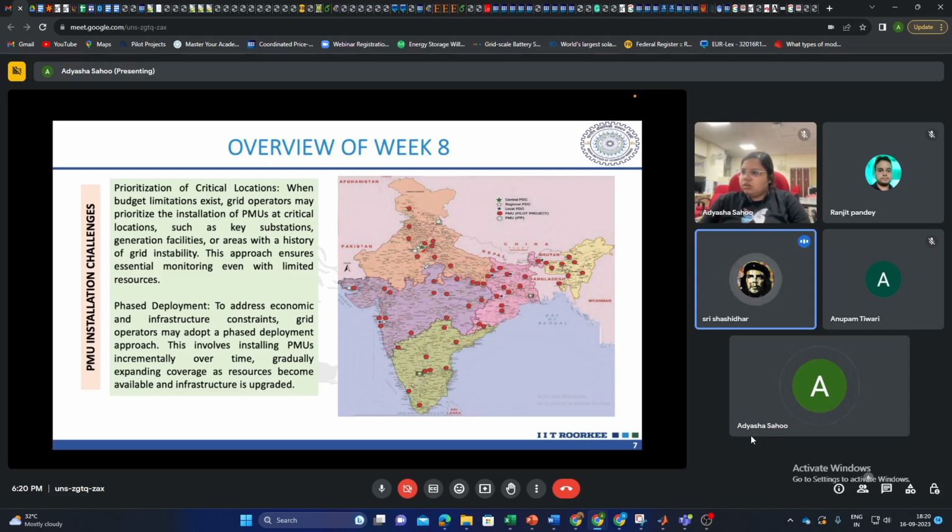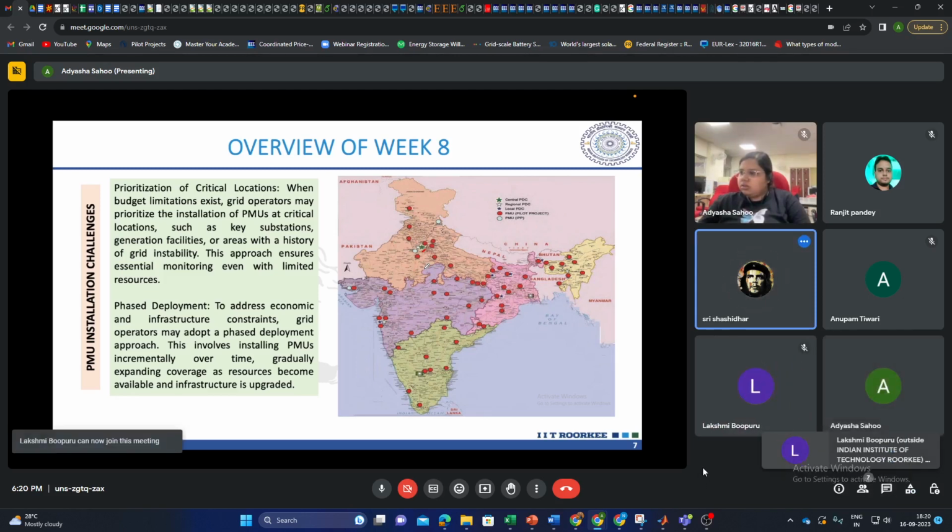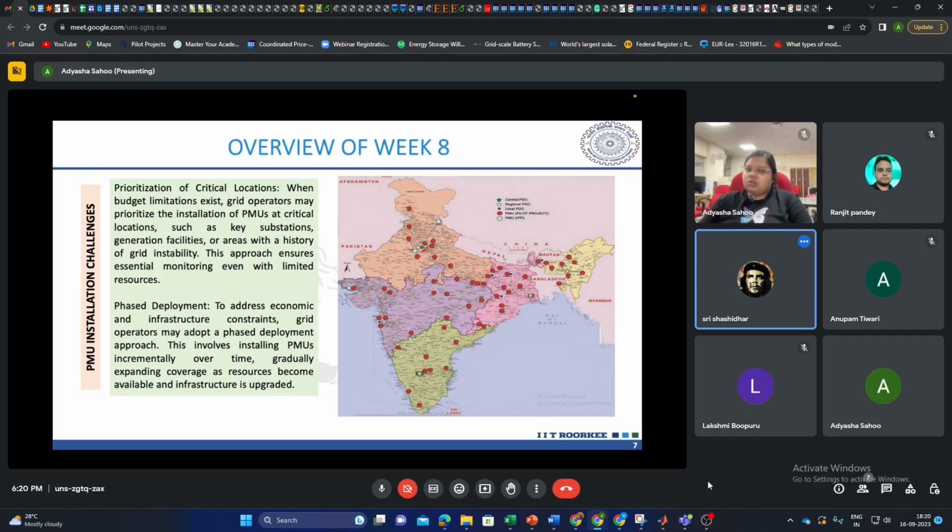Okay. Apart from that, with PMU, why do they require this same kind of data, even though they already have voltage and current levels? So you're saying each substation has its own meters and communicates that data to the area, but PMU covers more. PMU covers more area monitoring, and time synchronization is very important for data analysis.